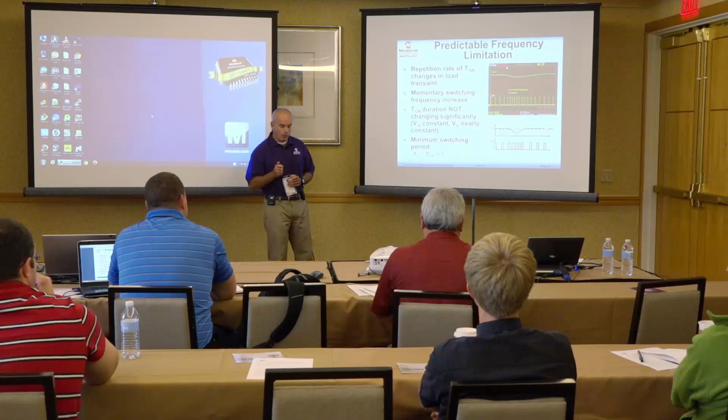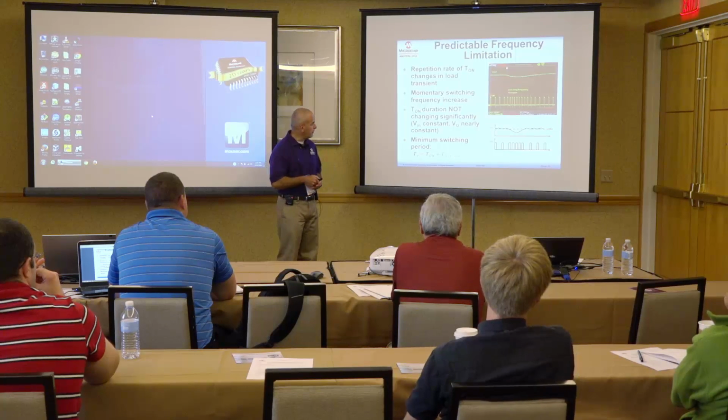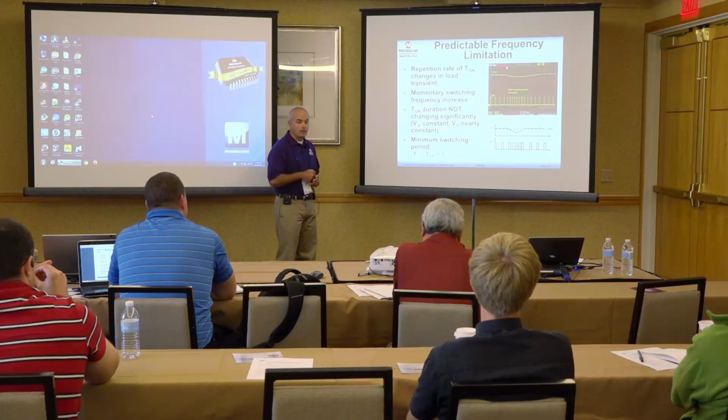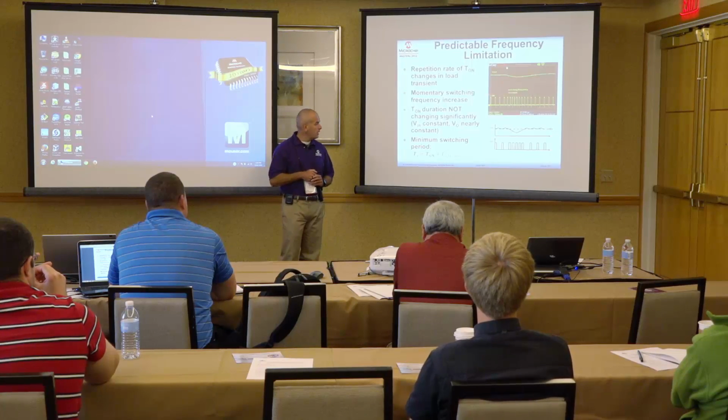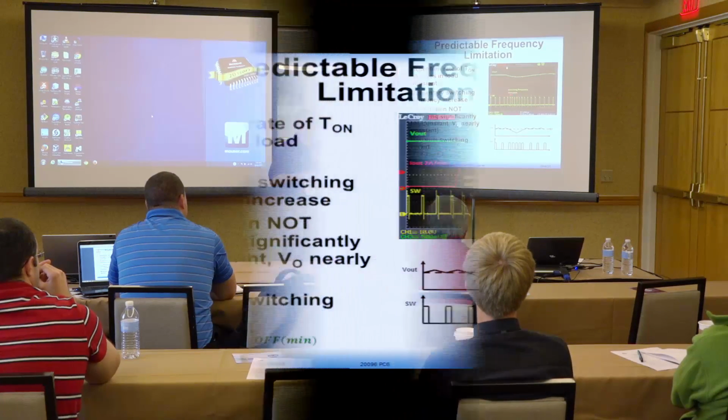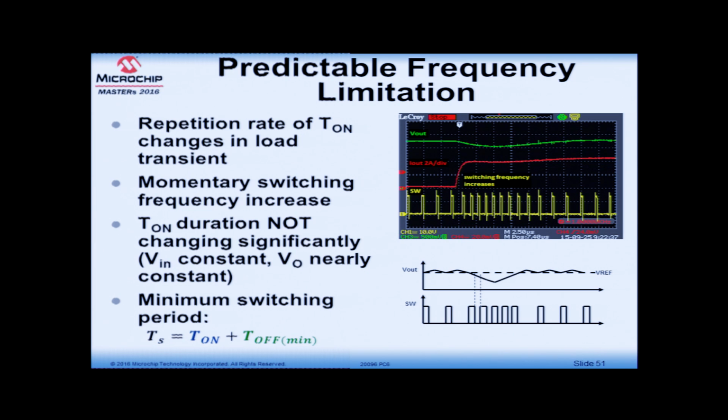This can be a big concern for many users. However, there are two important considerations we should make. First one is that the on time itself is not changing significantly during the load transient because the input voltage is constant and the output voltage is also kept relatively constant by the control itself. And we have a clearly stated minimum off time specification from the datasheet.